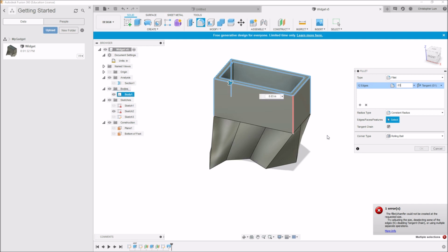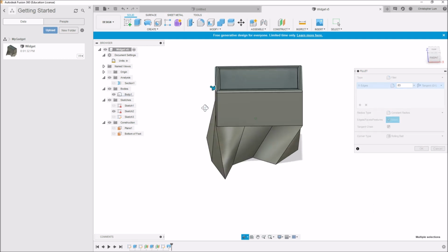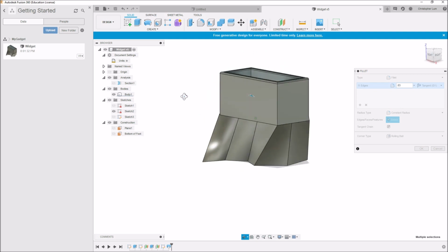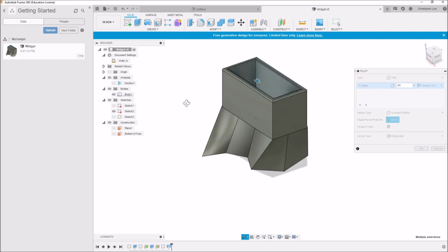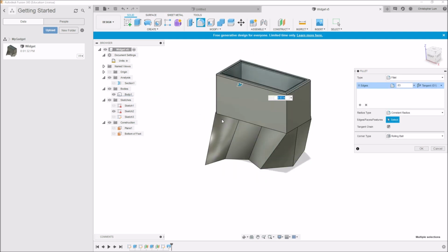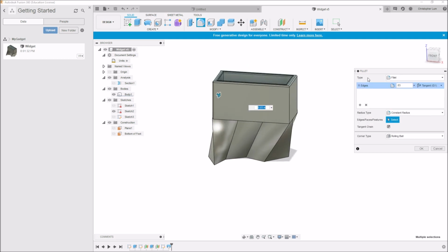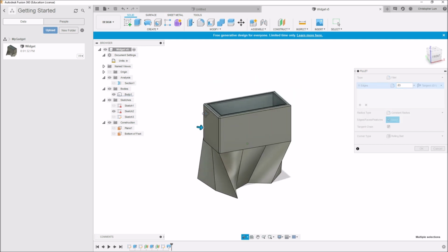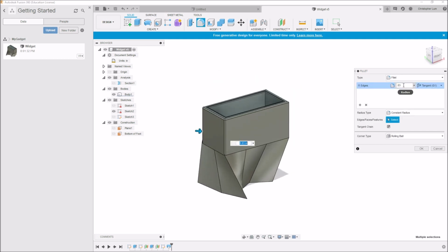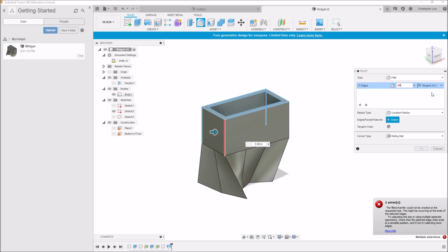So tell you what, let's deselect some of these edges. Whoops, there we go. I guess it didn't like that one edge, I think because of the odd geometry with the associated fillet there. So tell you what, let's just go ahead and use all the other edges. That's fine for our demonstration. So now that offending edge is gone, I think we can jack this up a little bit. 0.08. Sorry, I'm trying to type in 0.08.